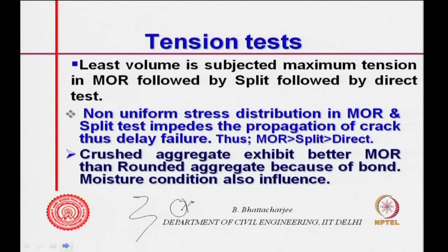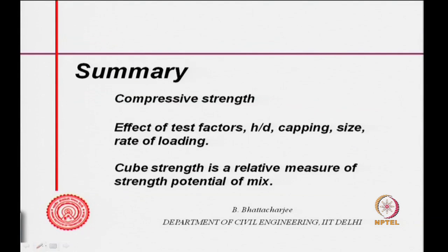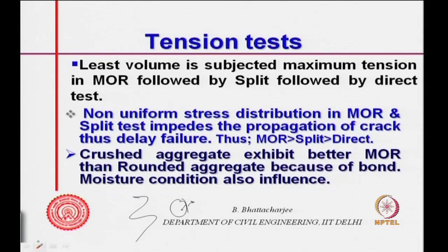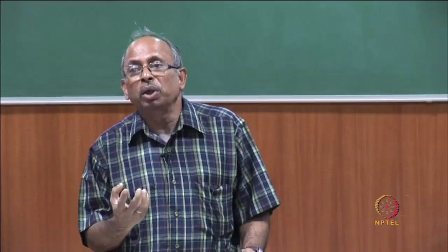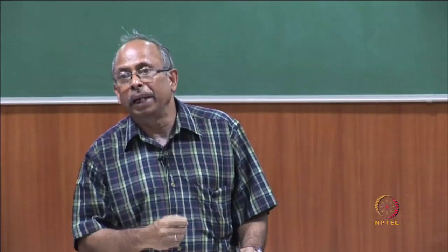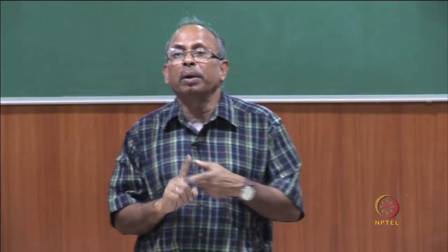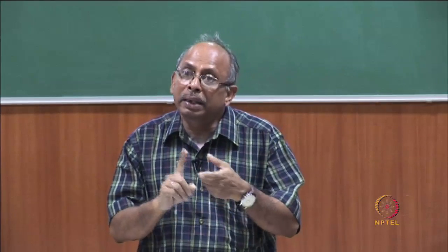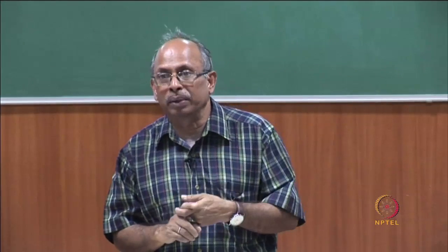Moisture condition also influences, but in a different manner. I think I have shown the diagram earlier: higher moisture content actually shows higher tensile strength, unlike compressive strength. Why?